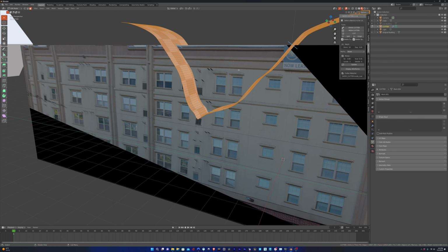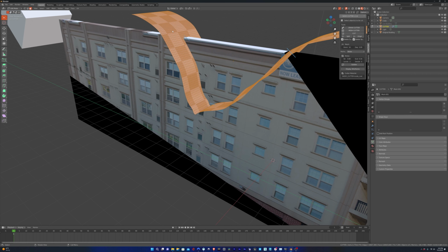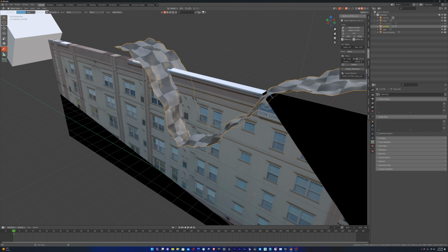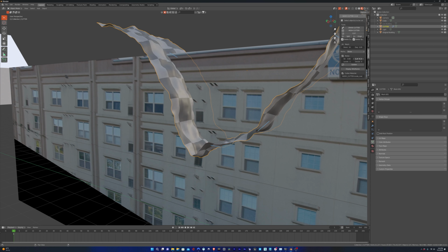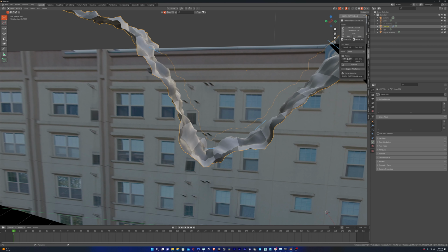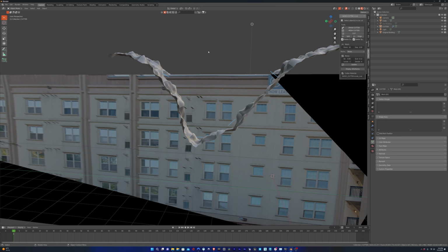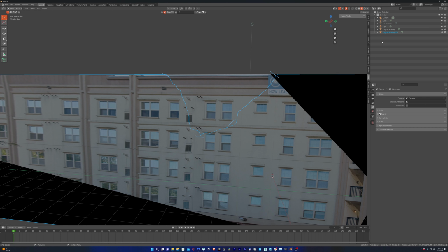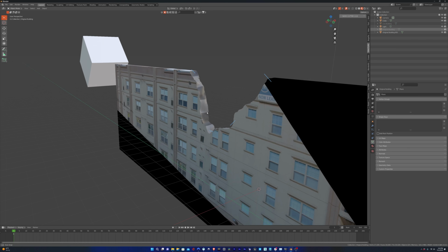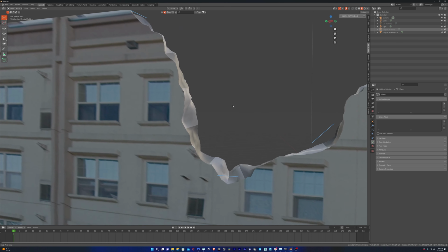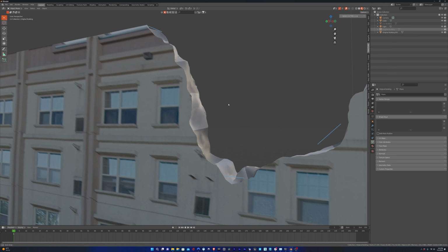Pretty good. And we have a pretty good density in this mesh. I just hit tab so you can view that, so you can see how much that mesh is subdivided. Maybe I can bring the scale down to 0.14 and update that. We'll do this again, but we'll do 0.12 and then 0.8 update. That's looking pretty good. Okay, so we'll select that, cut, and we'll hide our original building, see what that looks like. All right, that's pretty good.